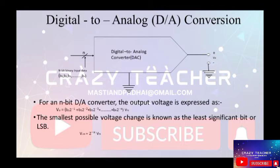So what is the smallest possible voltage change? To change the value, you can vary these bits, and since this quantity Bn into 2 power minus n has the minimum contribution, the smallest possible change that you can do is by flipping this particular bit Bn. And that way, this minimum change that is possible is 2 power minus n into VFS.